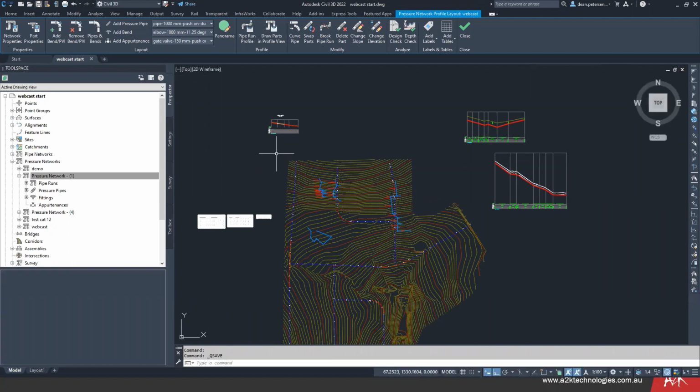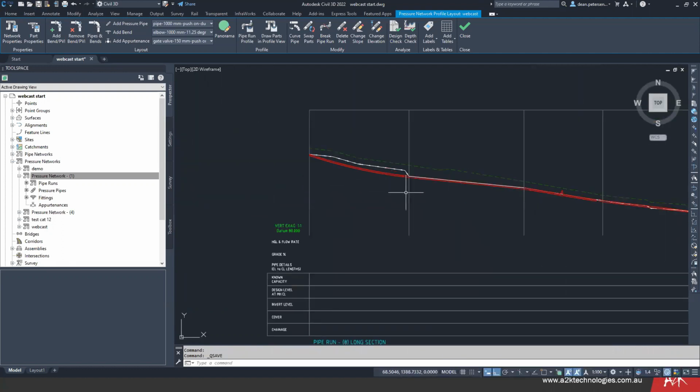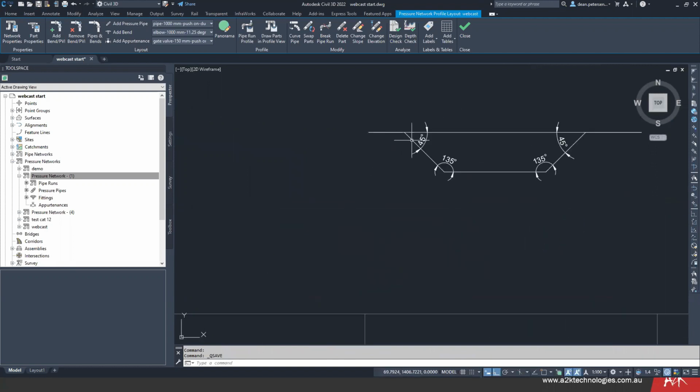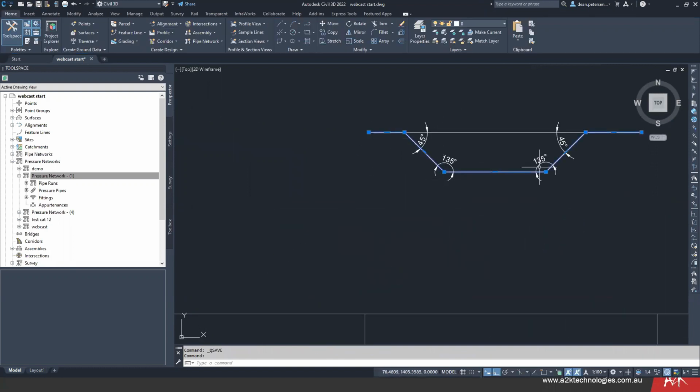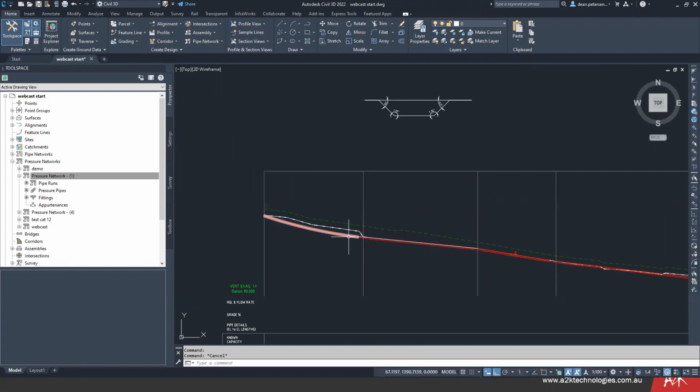And continue on. So other things we can do if you want a drop down in your pipes. This one here, I've just drafted a polyline, which has some 45 bends in it. We can bring that down into here and put it into my pipe.